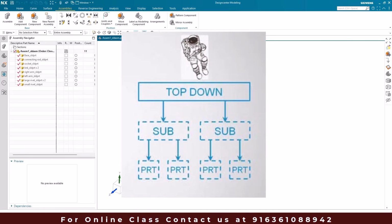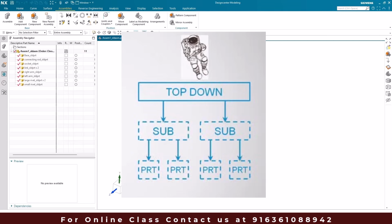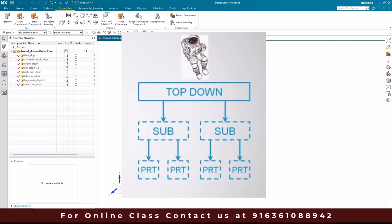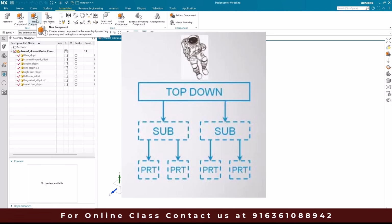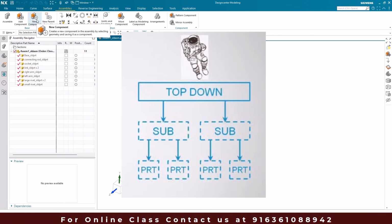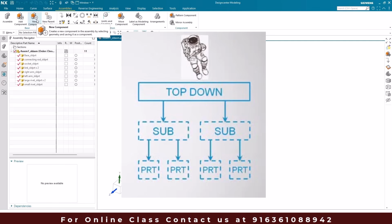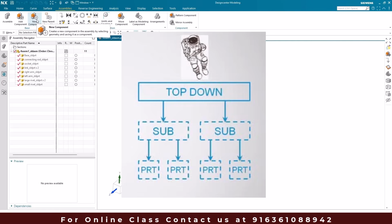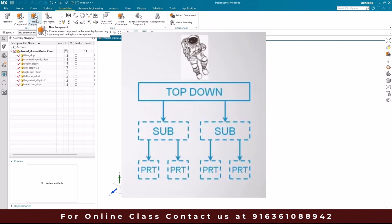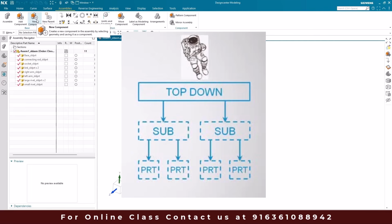So top-down assembly is a modeling that allows you to create a component at the assembly level. By using Create New, we can create a new component, and we are going to create the component in the assembly file itself. We will take advantage of an existing component's geometry and location in order to design a new component part. So this allows you to consider size, space, and interference limitations.